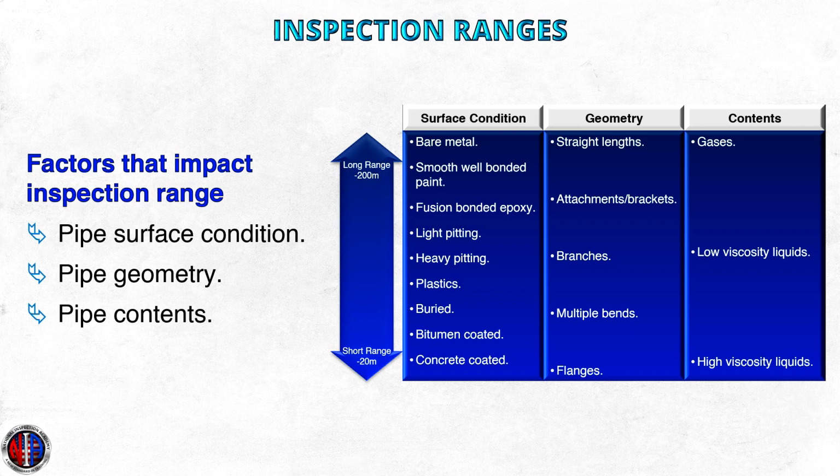The same is true with our contents. If the pipe is filled with gas, we'll get the longest range out of our scanning, followed by low viscosity liquids, then high viscosity liquids will give us our shortest range. And this is all based off the attenuation of the materials.